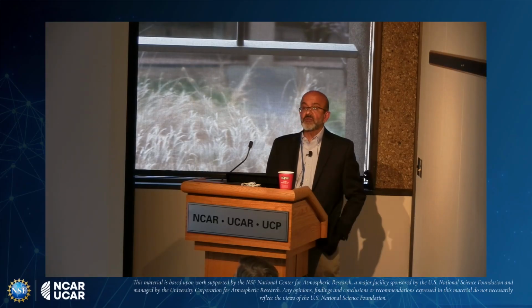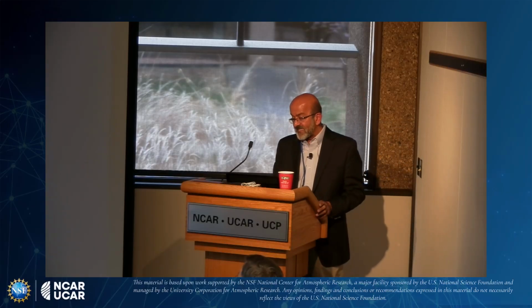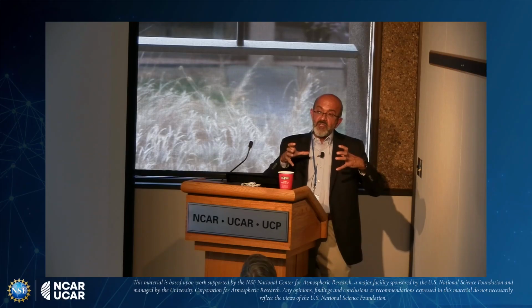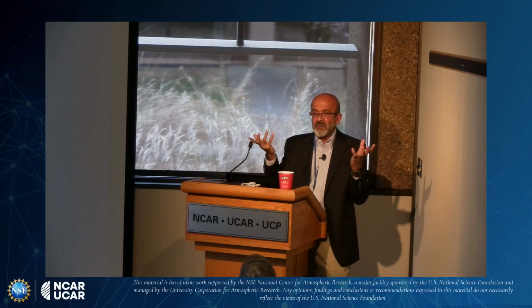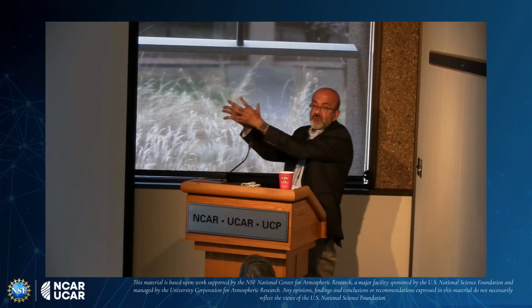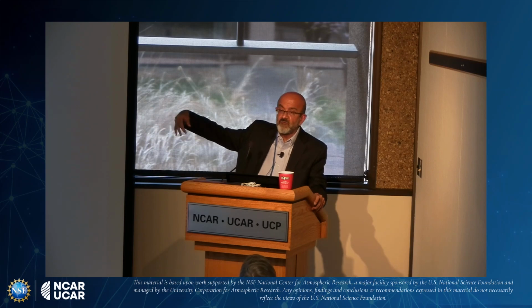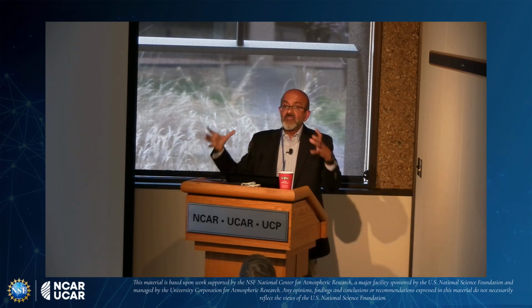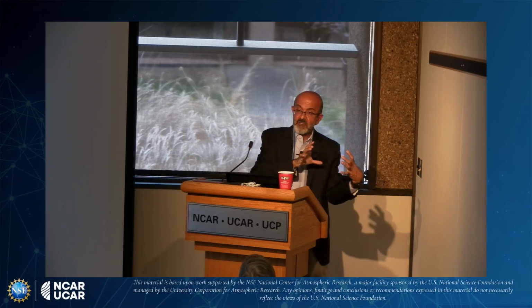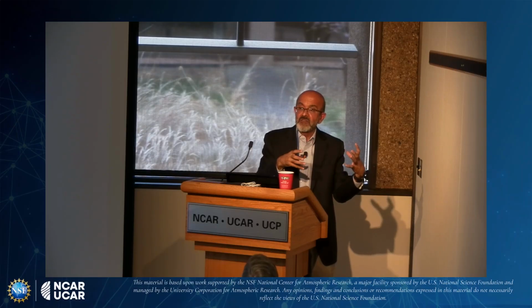So this is the interposer. The idea is what I would do: I'd go through the flow, and my last step would be the routing, and I'd get these design files. It's like Gerber files you send to a PCB vendor, right? I'll ship these design files to the interposer manufacturers, specifying the size, the interconnect, and all of that. They would fab that, and now I can optionally have them send me back the interposer, and I buy my own parts and connect them and solder them.